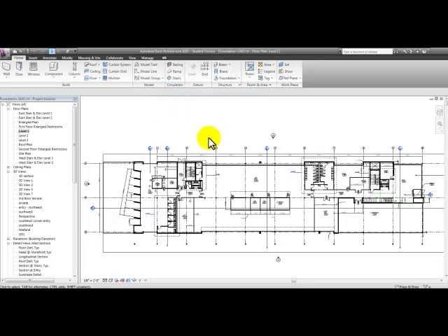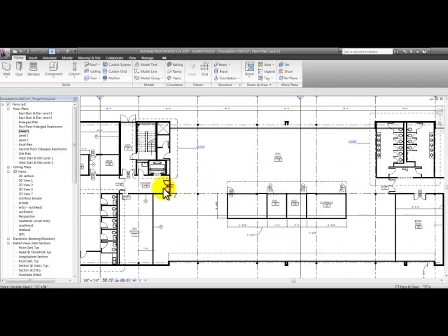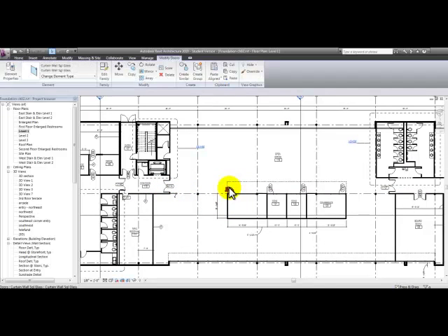And as most of you know, when you start a command or select an object, a contextual tab will appear along with tools in the options bar just below the panels as a choice. If you right-click the options bar, you can dock it at the bottom of the display screen or keep it here at the top. Just as a side note, if you're still using AutoCAD, you can access the CUI file to easily include this contextual tab.